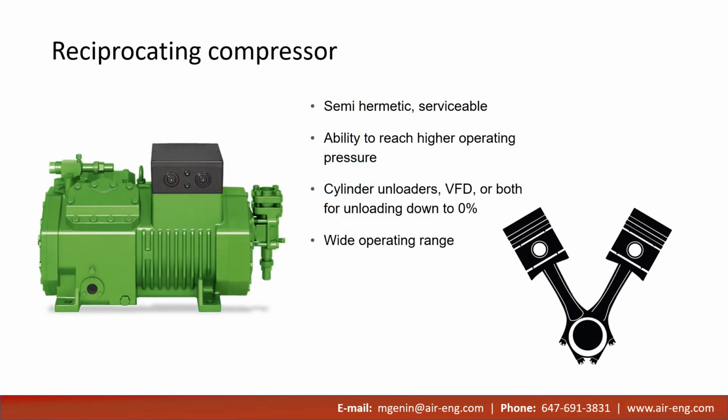So now with the understanding of the refrigeration cycle, we can go into further details on the components. Next, we'll discuss various compressor types and technologies, starting with reciprocating compressors. Think of them as a car engine. There are multiple cylinders and pistons which move up and down to compress a refrigerant. They can typically be driven by a VFD to adjust the speed of rotation. There are also cylinder unloaders available which can deactivate individual cylinders for capacity control.